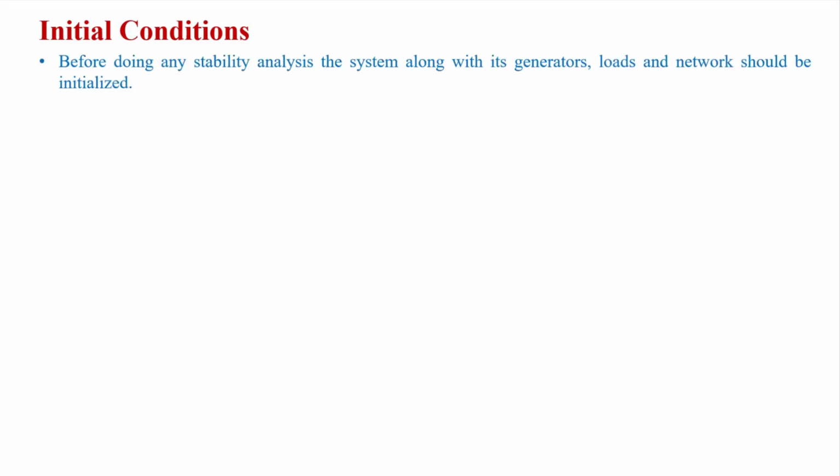So now we'll talk about the initial conditions. Why are initial conditions important? Because whenever we start solving any differential equation, we need the initial condition. I don't know whether it has been taught to you or not, but we will see it in the transient stability analysis and also small signal stability analysis. We need to initialize the parameters, then we can solve and reach the final solution of these equations we have derived, this DAE, differential algebraic equation, right? So now the question is how to initialize all these parameters. Let us see how we can do it.